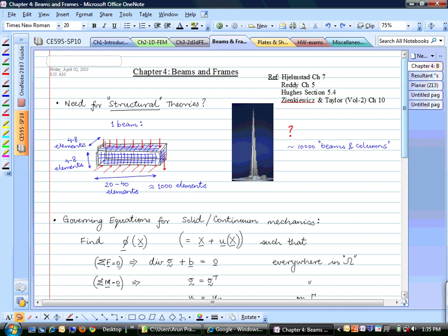It doesn't matter if you apply 100,000 kilonewtons or what. It's just going to give you a linear response if you are using a linear, small strain, linear elastic model. So the only thing you can gauge is qualitative measures: in what cases does the stress increase, what is a good configuration of holes, and those kinds of things.